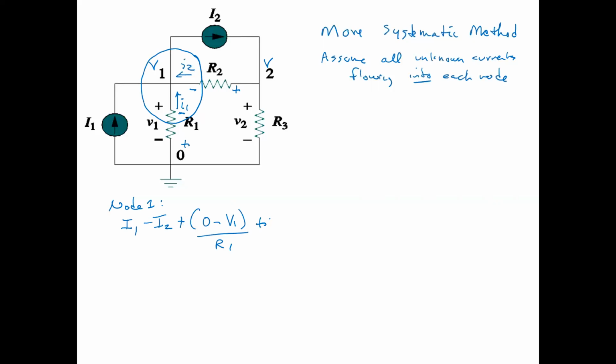And then the plus sign, and then we write the current for I2. And how would we express the current for I2 now that it's flowing to the left? With those polarities that we've labeled, passive sign convention, how are we going to express I2? V1 minus V2 over R2, right? Not quite. Which side of the resistor has the positive sign now? V2 has the positive sign, right? So it's plus V2 minus V1 over R2, right? And that equals 0.